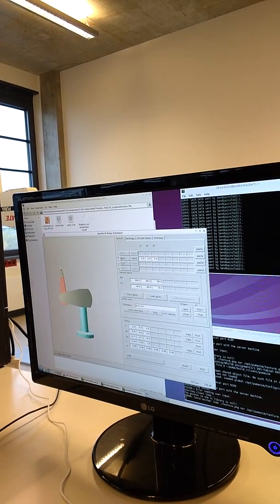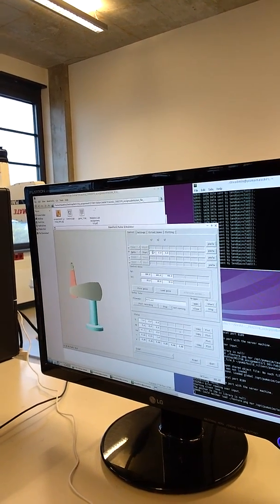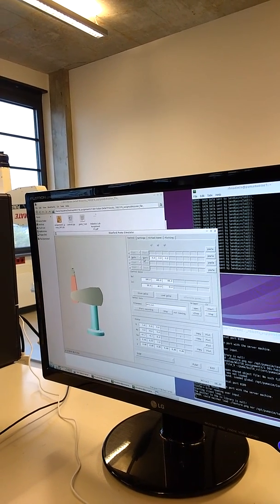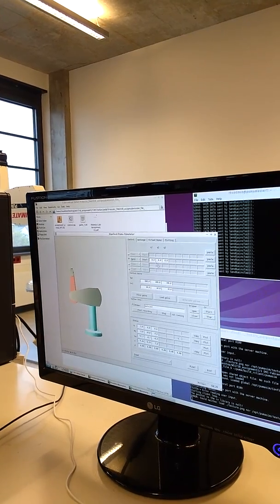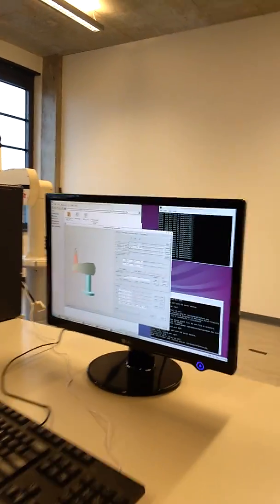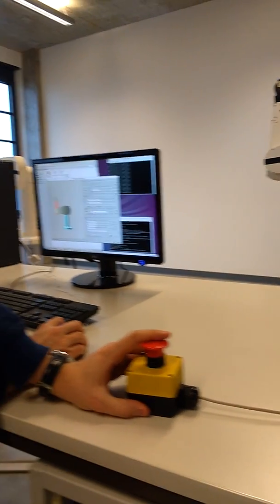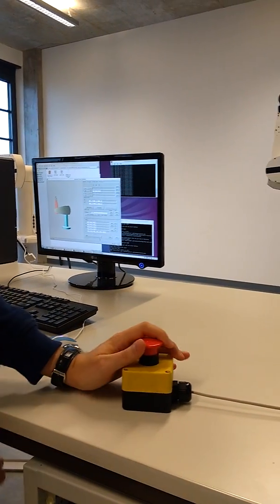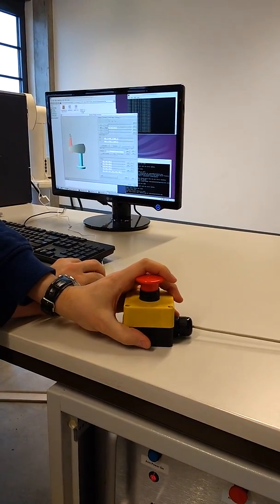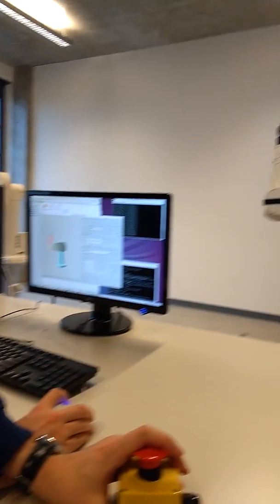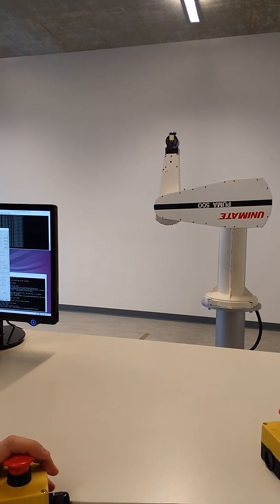Make sure that the robot is not too far off from the position you send. Right now it should be close to 0. Actually, well, we'll see if this works because we reset it without being super in the 0 position. Yeah, but it should be fine. Okay, so again, before you start the robot, maybe put it in float mode, start the robot, and now you can press start to execute the controller. Okay, and it'll just move to the position.